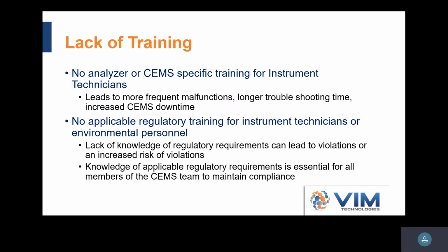So there's lack of training. I know when I was a technician, I was way better at troubleshooting and problem solving on analyzers that I had training from the manufacturer on. I mean, you might have 3 different NOx analyzers and they're using the same technology. They might all be chemiluminescent analyzers, but they function a little differently. So getting training on the specifics of each analyzer makes it easier to troubleshoot, and you can fix problems more quickly, and then again, minimize that downtime and get the system back up and running.